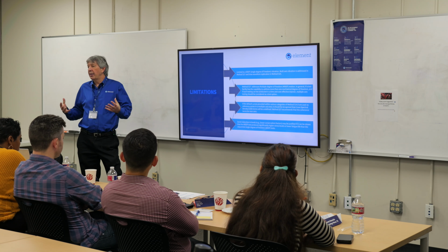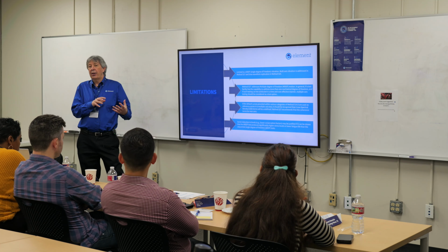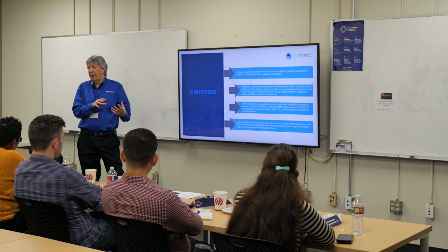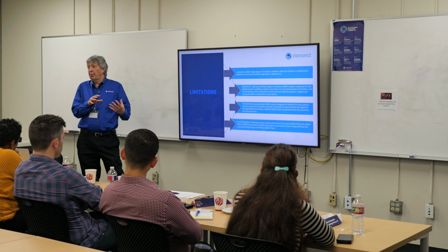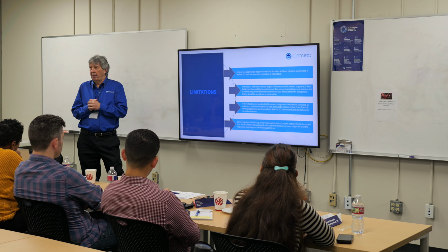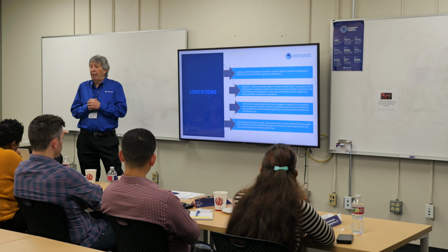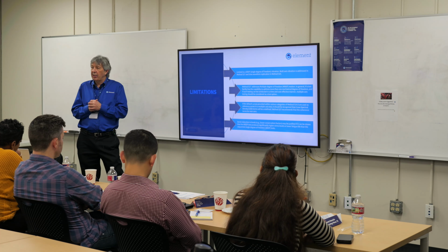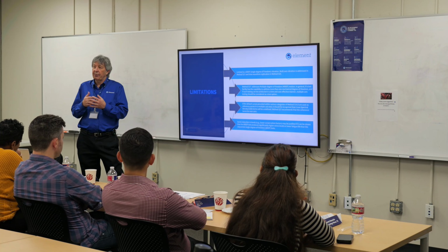So there's no definition. If you're using the vibration curves out of 514, what it's saying is more than likely you're not going to hit the coherence number that you need to hit, because all the drives are going to be basically the same. But if you use some phase shifting, you can get the coherence down. There's a few things you can do.